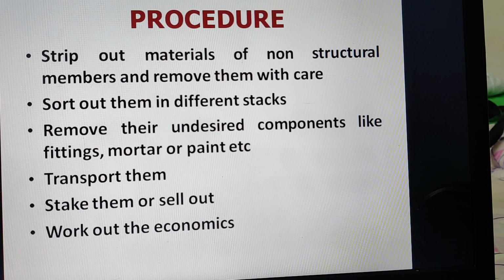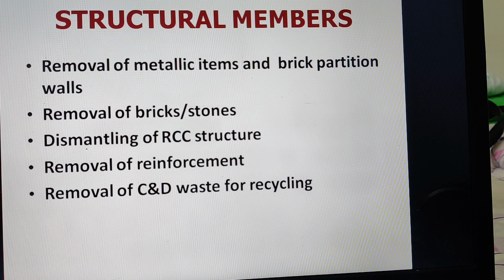If we talk about the procedure, we first strip out materials of non-structural members, remove them with care, and sort them into different stacks. Undesired components like fittings, mortar and paint, etc., are to be removed if required, and then we can transport them, stack them or sell them, and work out the economics if they are economic.